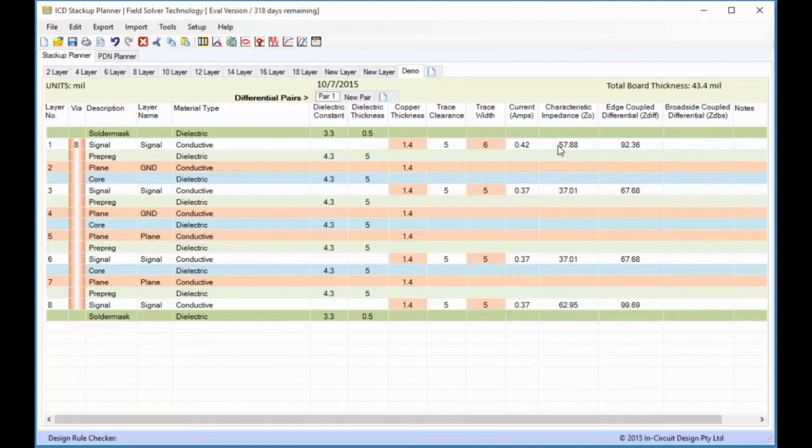This tool has a field solver in it. So as a result, based on all the material information that you provide over here, it can give you very accurate readings as to what each one of these layers is going to do. And that's a good thing, because in most rule sets you can go in there and you can make those changes accordingly based on the certain layers.